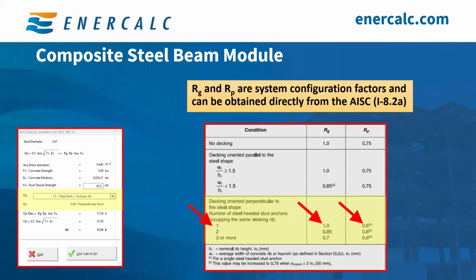Or you can specify a particular composite percentage that you want to achieve. And I'm going with the third option here, and I'm choosing a minimum 50% composite. So I'm just starting with a 50% composite and going to see what's going to happen. So this concludes all of the input data under the General tab, and we are ready to move forward to the next tab.